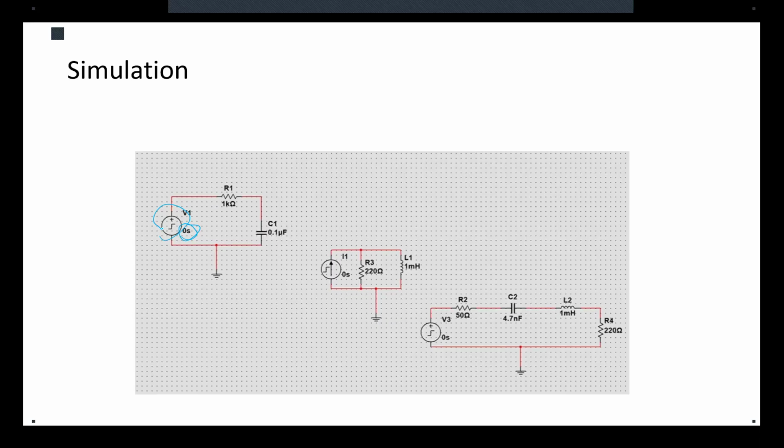There is another value, which is the time that you want the step function to rise from 0 to the final value. You can't make that instant, so 0 is not enough. Okay? With a simulation, it would create a problem with the numerical solutions. What you have to do is put a very, very tiny number. I put 1 nano, so it starts from 0, and in 1 nanosecond it gets to the high voltage. So you have your step function. Are we clear? For all the sources, both voltage and current.